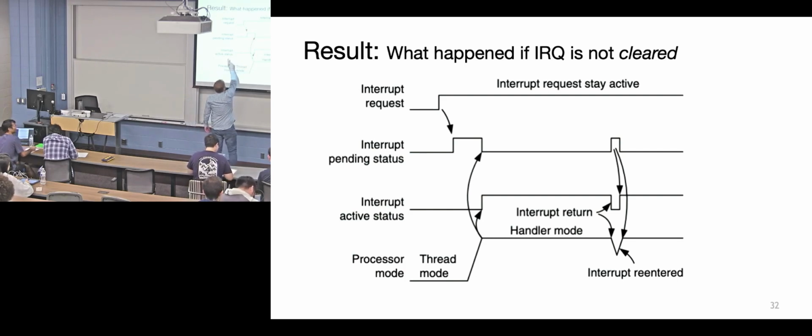All right. So anyways, the request went off, or the request got captured, and something went into pending. Pending is deasserted because you're in the interrupt. When the interrupt is disabled, now pending can go back up. So pending all of a sudden says, oh, wait, where are my interrupts? Then it reasserts pending, and this basically goes right back into that interrupt.